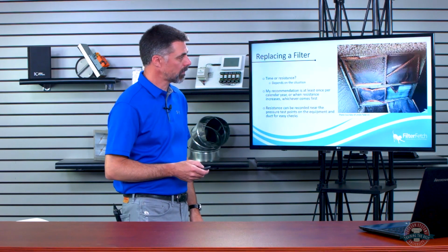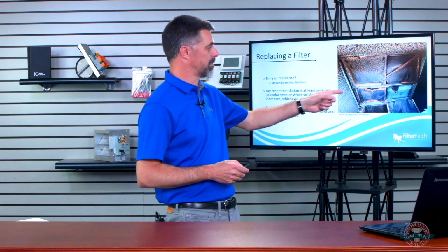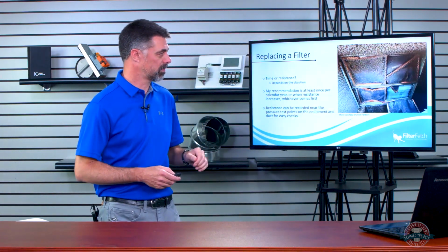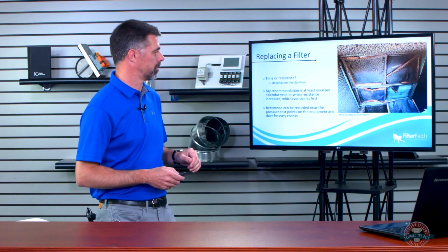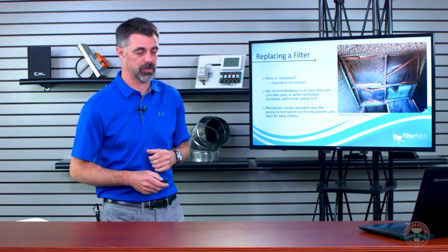Now, obviously, these filters were in there just a little too long. The guy that gave that picture to me said he thought they were in there about 5 years, so they could have been changed a little bit before then. All right, again, once per year or when the resistance increases.